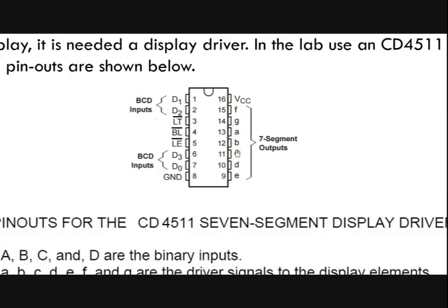Okay, so you can see not in order. So therefore you need to be aware. Okay, so which is A, and then this A need to be connected to pin A of 7 segment. So this one not in order. And then you go to the left side, D1, D2, D3, D4 is the input. Okay, input coming from the microcontroller. The value must be in 4 bit. Okay, 1, 2, 3, 4. The decoder only receive 4 bit from the microcontroller.